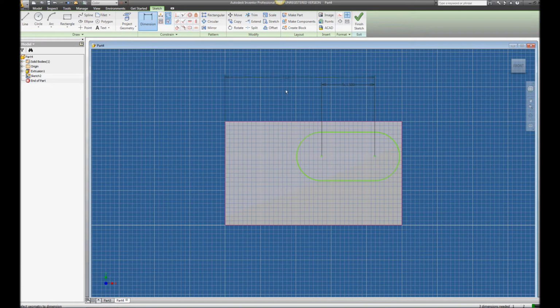There it is. Alright, and we need to type in some sort of equation. It's telling us it's 4/5 of the overall plate width. Plate width is D1, and we need to multiply it times 4 divided by 5. Perfect. Now, what's great about Inventor? If you want to divide 4 by 5 out and type in 0.8, then you can do that, and it works. Alright, so we have a function of x here, function of x here, telling us we do have two equations.